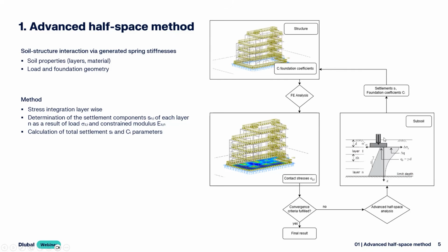The contact stresses are put as load on the subsoil, and the stress is integrated layer-wise, and with the stiffness of each layer, the settlements are calculated, and also the foundation coefficients. At first settlements layer-wise, and then the total settlement of all layers together, and then the foundation coefficients are calculated.